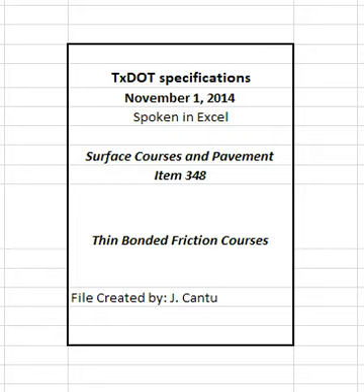4.4.2.1.9 Trial batch production. Provide a plant-produced trial batch upon receiving conditional approval of JMF1 and authorization to produce a trial batch, including the WMA additive or process, if applicable, for verification testing of JMF1 and development of JMF2. Produce a trial batch mixture that meets the requirements in Table 5 and Table 9. The engineer may accept test results from recent production of the same mixture instead of a new trial batch.